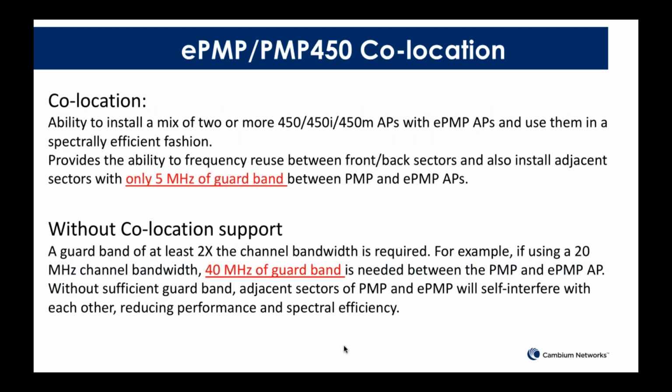Okay, so how does it help you? Without collocation, you need an additional guard interval between these two systems. With collocation, you can do only 5 megahertz of guard interval between PMP and ePMP APs, and that's the recommended way of doing it. But we know customers who actually do frequency reuse on the same frequency with PMP and ePMP systems.